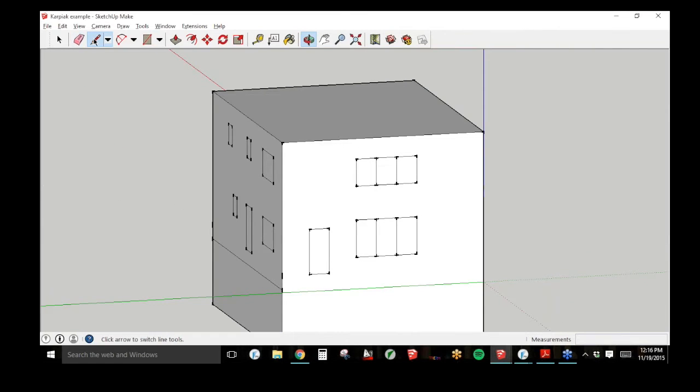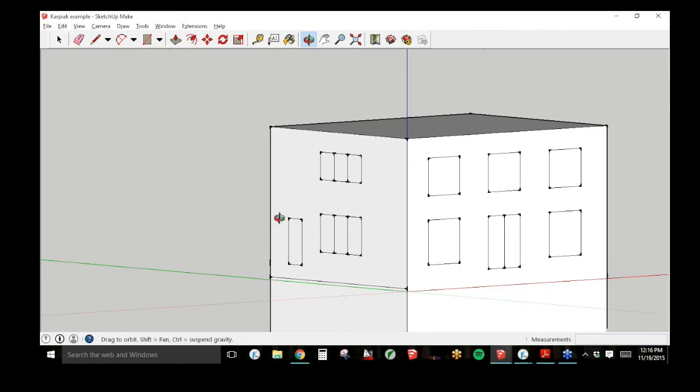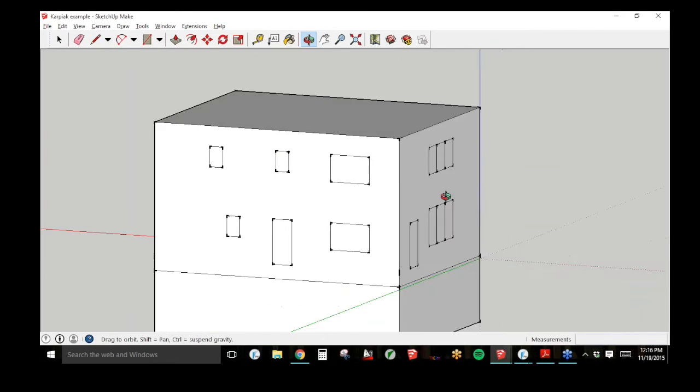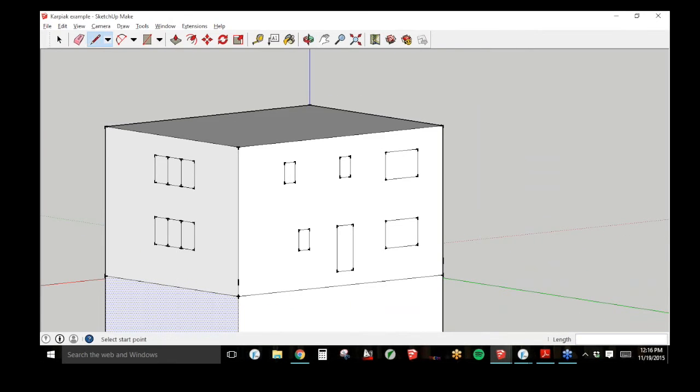While I'm doing this, I might note that, let's say you have a rim joist condition or something right above this. You will not make that a separate component or a separate sliver in the WUFI Passive model. The real way to account for something like that is a thermal bridge calculation. So don't do a little sliver like this and say this is your rim joist and create a different assembly for it. It would be a thermal bridge calculation rather than doing that.